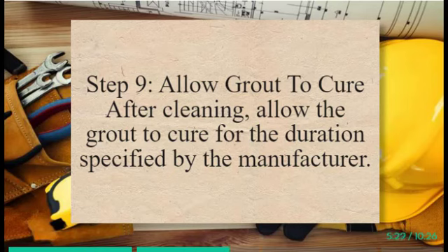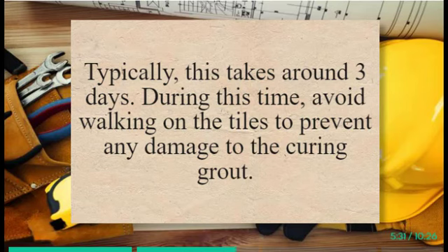Step 9. Allow grout to cure. After cleaning, allow the grout to cure for the duration specified by the manufacturer. Typically, this takes around 3 days. During this time, avoid walking on the tiles to prevent any damage to the curing grout.